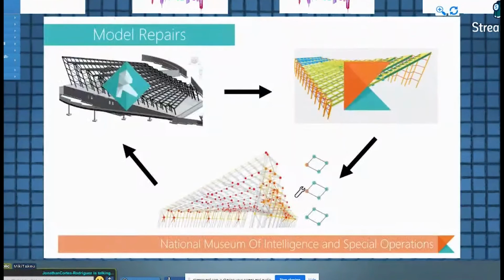Another example is that Konstru has a variety of features that are more than just talking about data and containing. It talks about the idea of flexibility and even fixing. So in this case, if you have a model that might not be connected, let's say you have a couple elements that are just ever so slightly off, we have what's called framing repair. Konstru can take a given model, upload it from Revit or eTabs or whatever your platform of choice is. It can analyze the elements and connect them together to ensure that connectivity. And as we all know, when you're dealing with building data, you want to make sure things are accurately connected, obviously to reflect its real state, and ultimately to also show the building correctly. So for documentation purposes, you definitely want the drawings to show the elements connected.